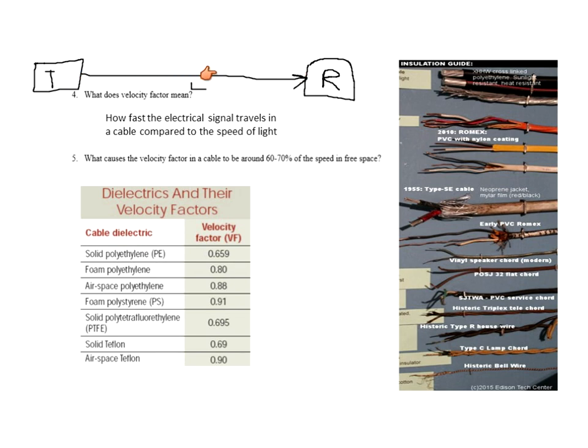Now, ideally, in this transmission line right here, this wire connecting this to here from there to there, we would like it to be instantaneous, or at the very least at the speed of light traveling down there. So when I put a signal in here, it takes time for the signal to get over there, a measurable amount of time. Sometimes we call that latency, sometimes we call that propagation delay. But in a cable, the wave always travels a little bit slower than the speed of light, or the speed of a radio wave in free space.